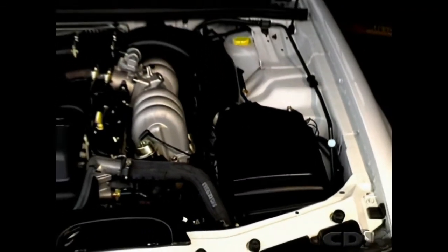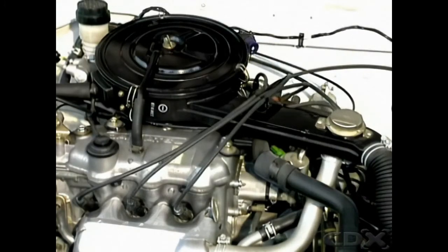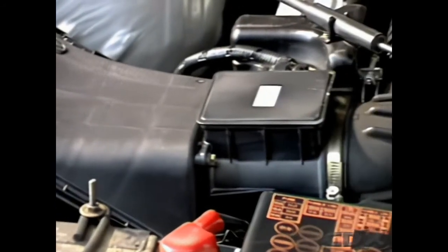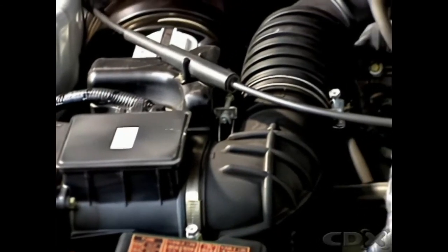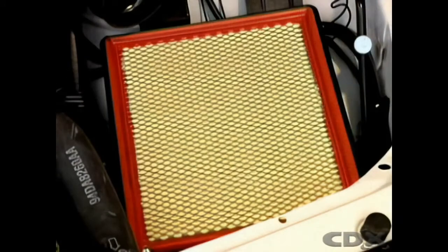An air cleaner on a multi-point electronic fuel-injected engine usually has a different shape from that on a carburetted engine, but it serves the same purpose. In many vehicles, the air cleaner is mounted where it can get cool, clean air. This air is then carried to the throttle body by a long, flexible duct. Inside the air cleaner, a filter element of pleated paper filters the air and reduces noise.